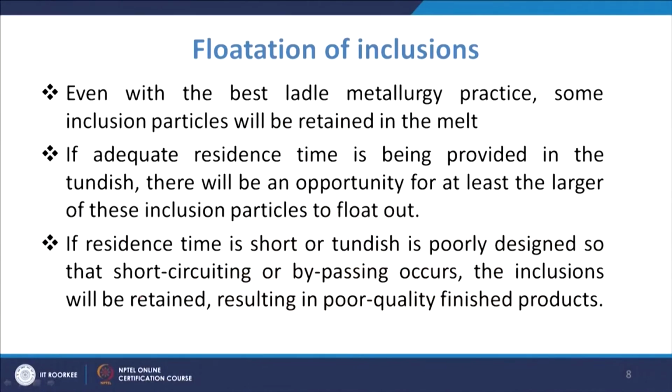So, you have to see that you avoid this short circuiting or bypassing. Mostly it occurs because of poor design of the Tundish, or because you have not properly used the flow modifiers in the Tundish.